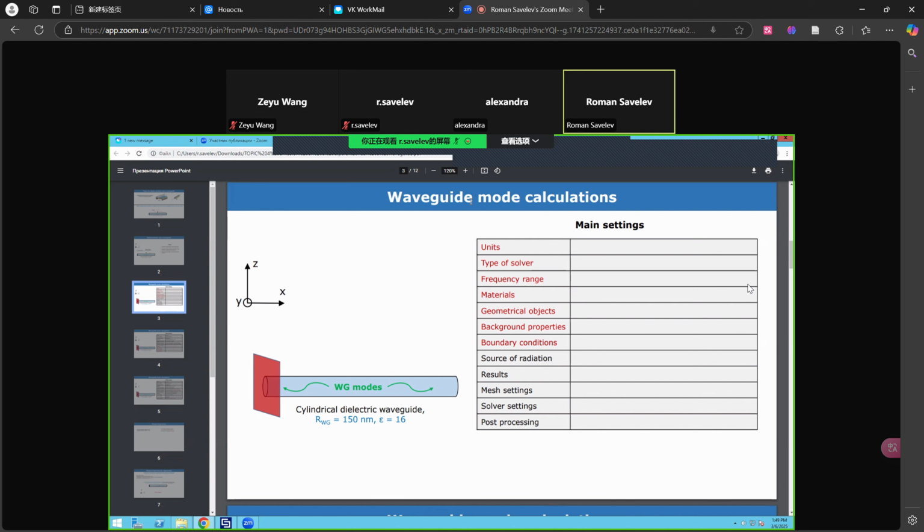Yes. First, you need to understand what problem we're solving. We only want to find the modes of the port. So we're not going to excite this waveguide at all. For now at least, we just want to calculate the modes of the port. And in this case, that's true. The size of the cylinder won't matter at all, so you can take it arbitrary.